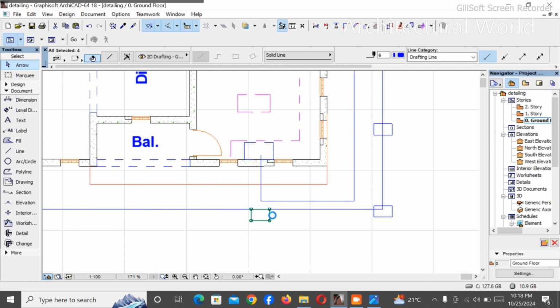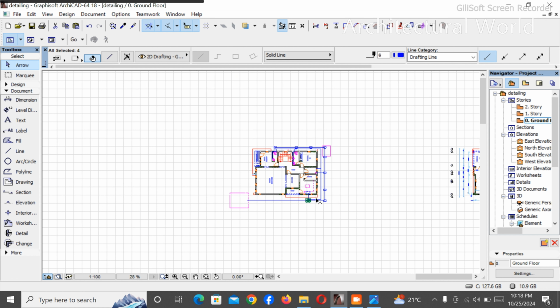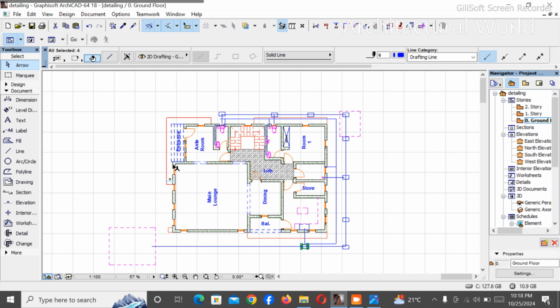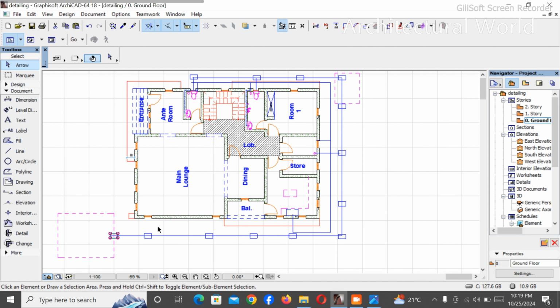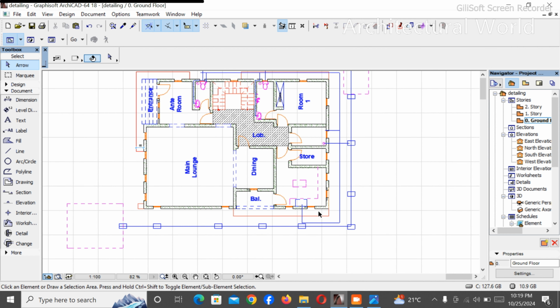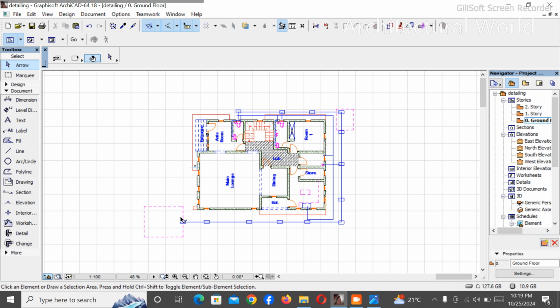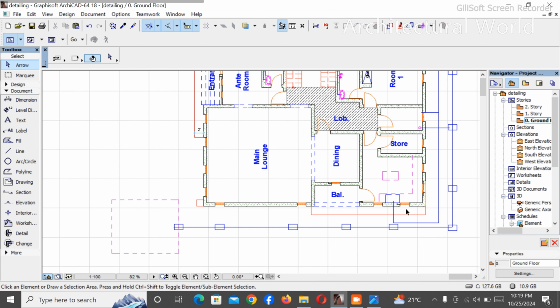In case you don't want to be using all these chambers, like I said, if you want to save cost, you can run all this through the front of the building, like the first process I indicated. Or you work all these chambers. The chambers are many, so I will advise you change your design. Now this is the septic tank. If you go through this method, you need all these chambers to get to the soakaway. But if you go through this method, you only need one chamber, two, three, four, five.